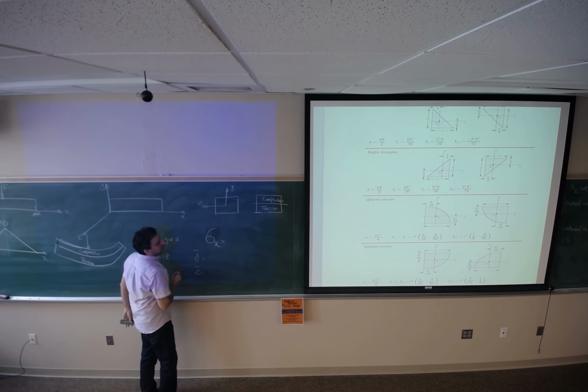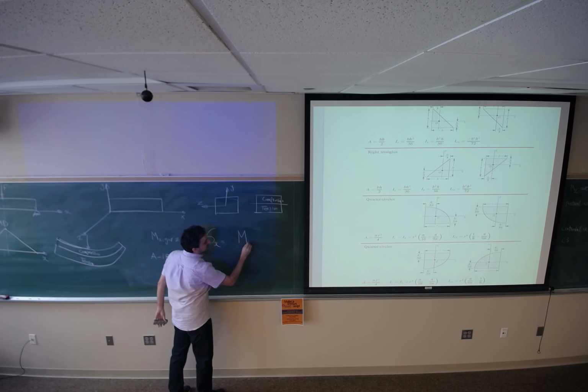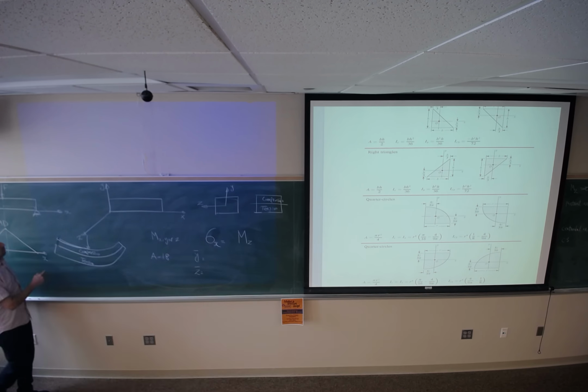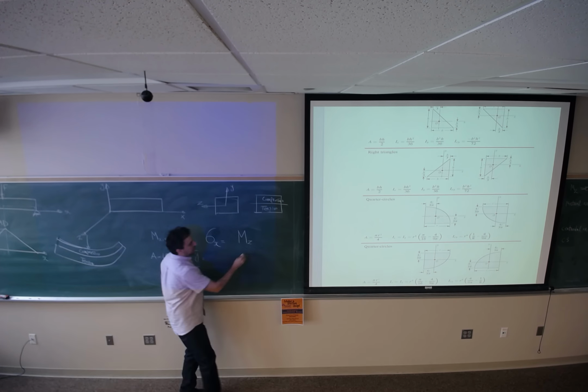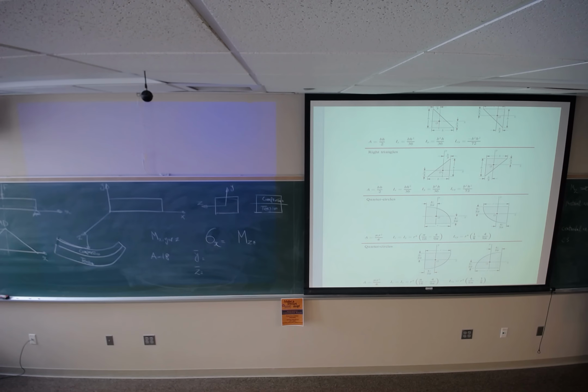Then the sigma has this relation with M. If we are given Mz, which is the maximum bending moment at the middle of the beam, and you are looking for the normal stress at this point, you just need to measure the y distance of this point from the centroidal axis, which is this distance.